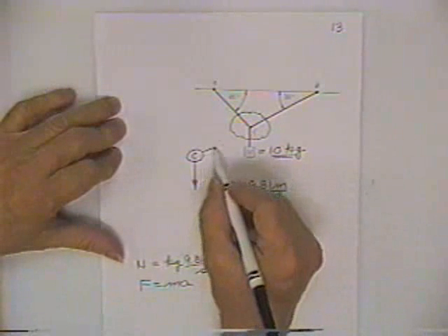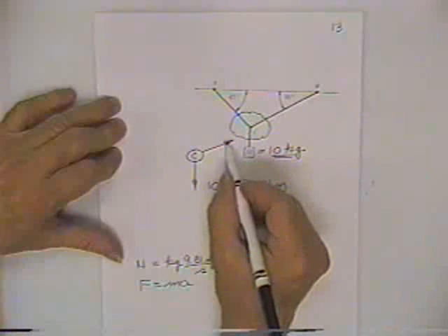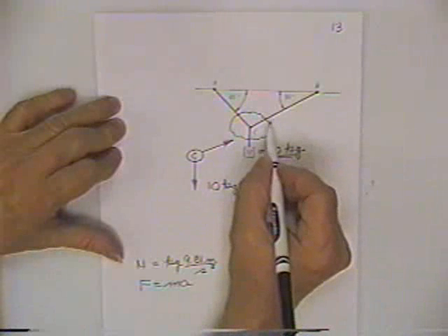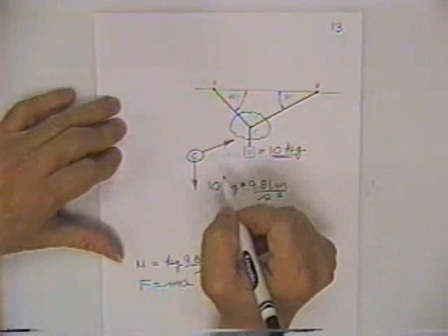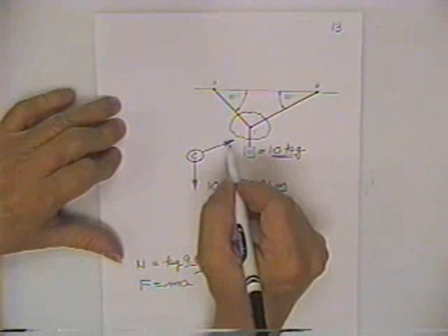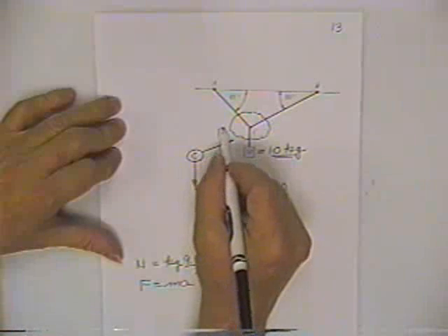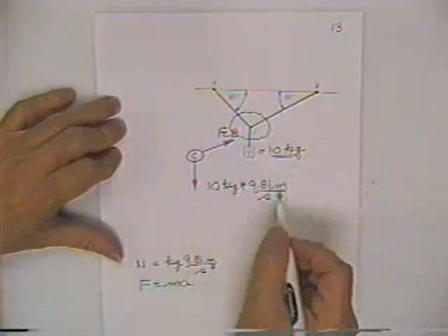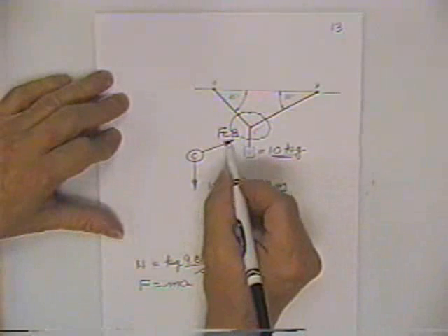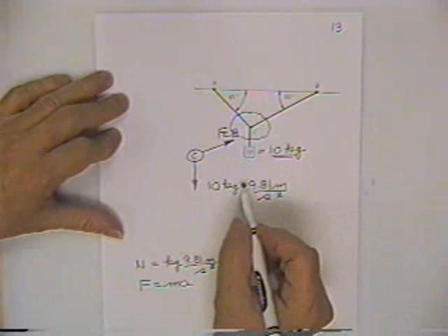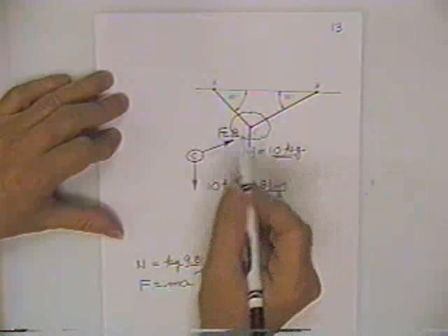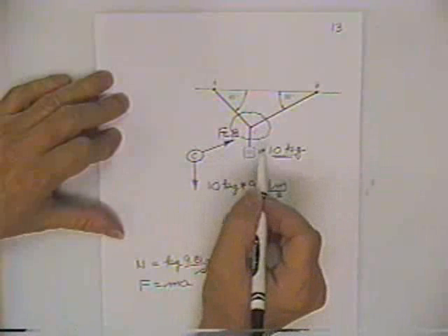Now, on this side, we have a force. It's absolutely critical that when you cut this wire and show a free body down here, you do two things. Number one, you must give this arrowhead a name. A good name for that one might be FCB. It's an acceptable name since it's cut through CB. And you'll notice that I gave the arrowhead a direction. It's probably pretty obvious that the force is a pulling force, a tensile force, since it's a cable and since the weight is pulling down on the cable.